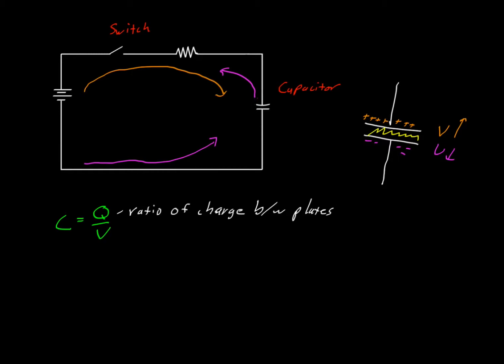All right. So what if we put capacitors in series and in parallel? Well, capacitors work the opposite of a resistor. So in parallel, capacitors are all exposed to the same initial voltage, so therefore their capacitances add. So in parallel, capacitance total equals C1 plus C2 plus C3 all the way to C sub n. All right.